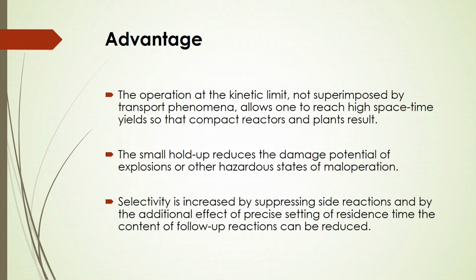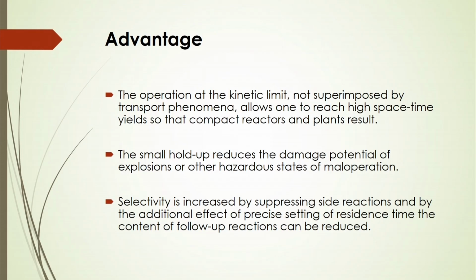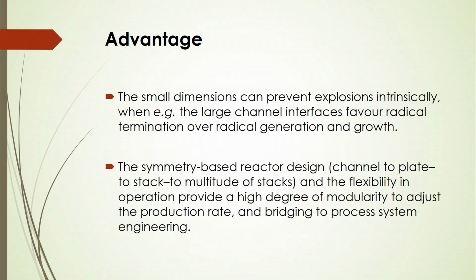And the small holdup reduces the damage potential of explosions or other hazardous states of maloperation. You can also get operation at the kinetic limit, not superimposed by the transport phenomena, which may allow one to reach high space time yields, so that compact reactors and plants result. And selectivity is increased by suppressing the side reactions, and by the additional effect of precise setting of residence time, the content of follow-up reactions can be reduced.